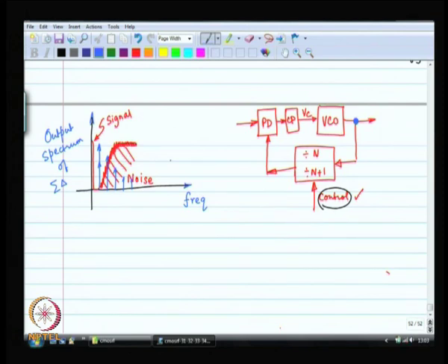And interestingly enough, the output of the VCO was also looking like that, just modulated at F naught, F output. The control voltage for the VCO looked very similar. In fact, the spectrum of the control voltage for the VCO also reflected this behavior. There was some DC and there was the fundamental at the raster frequency and its harmonics.